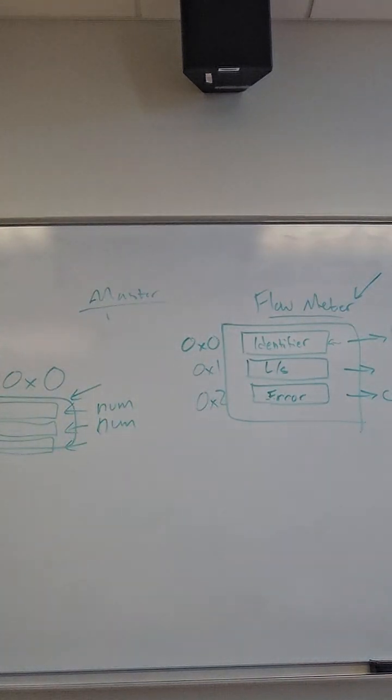So that's what we're seeing here. This is an actual Modbus device, an actual data sheet component, and it's telling us what is in each and every one of these data sheet slots. So here, an address 0x001D, address number 30, I think that's 30 in decimal. Okay, read or write, right?